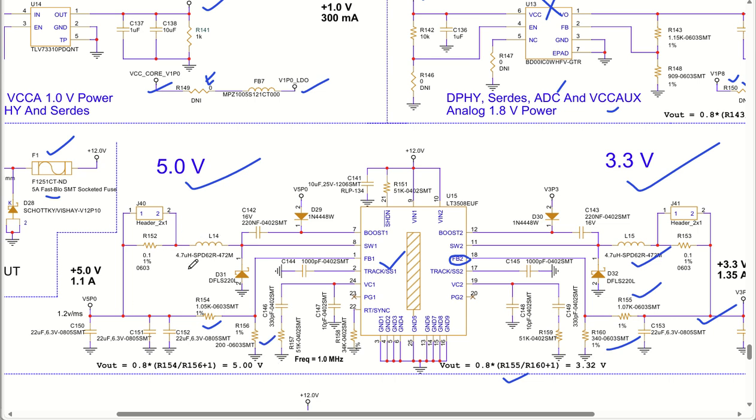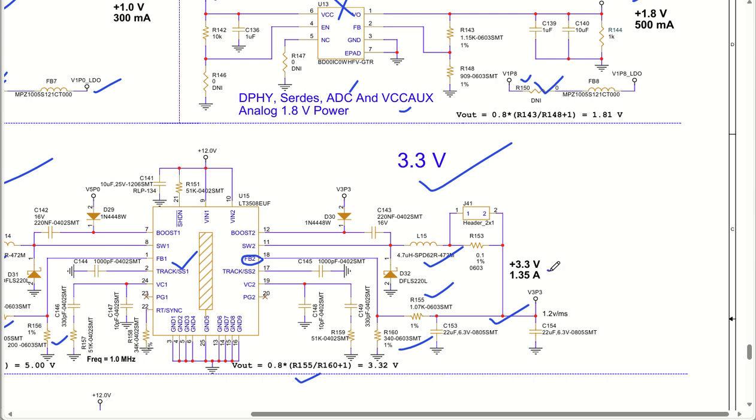You have the inductor as well at this location to set the output voltage to 5 volt. And proper bulk capacitors are used for these two voltage levels. The 5 volt level uses 3 numbers of 22 microfarad capacitors, and the 3.3 volt level uses 2 numbers of 22 microfarad capacitors.